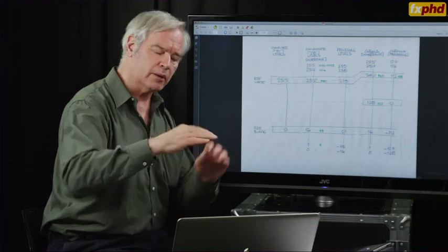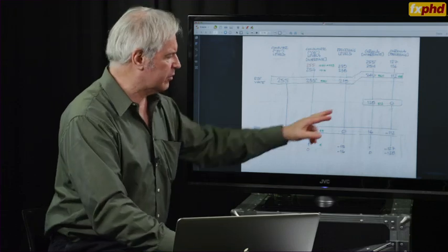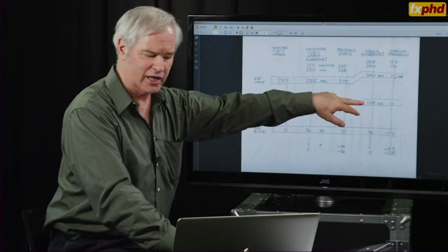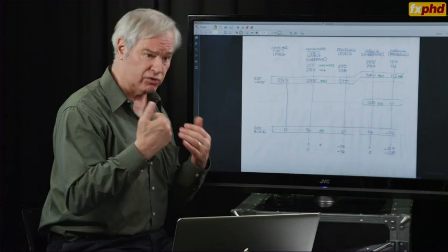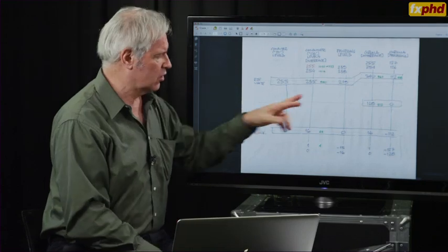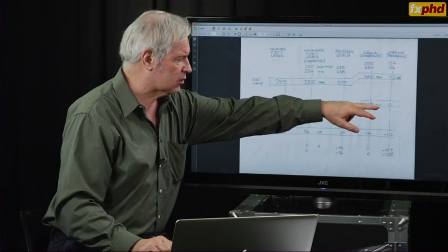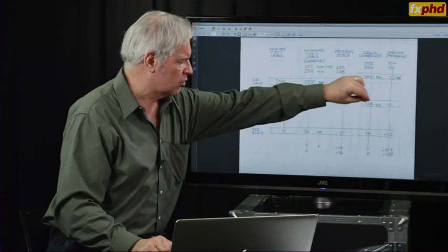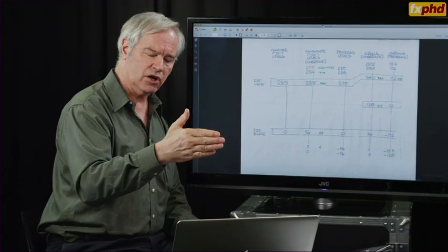Those 2 chroma components end up being bipolar above and below 0. Some people will say that they're centered on 128, but I consider that 128 to be the interface offset. The first thing that I do as a mathematician, signal processing guy, is subtract it out. So I prefer to think of chroma 0 being the grayscale, and then the chroma components in 8-bit space range plus minus 112. That's a detail of YCbCr space.